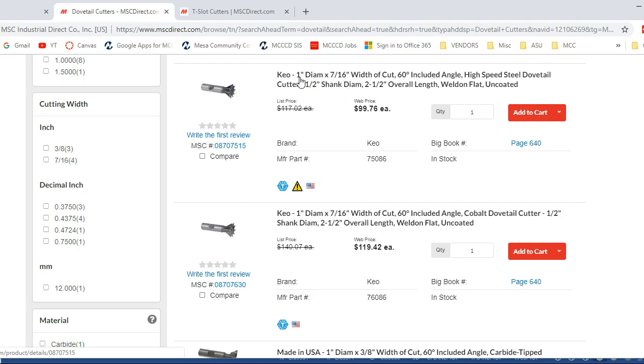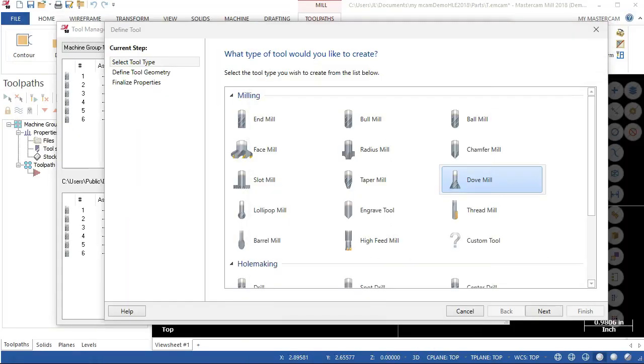1 inch diameter, and usually what I do is I'll set that between 5 and 10 thousandths oversized because of the variation, deflection, materials that we're cutting. I want to comp this in to bring it to size. Bringing the dovetails to where they have a nice smooth fit into geometry is always difficult. So we can count on clearances, we can count on the locking mechanism to do part of that for us, but I don't want to start off oversized.